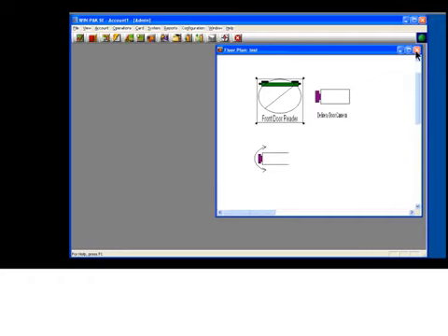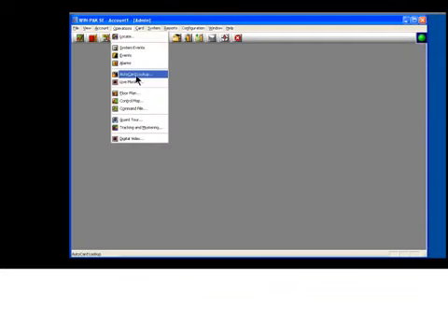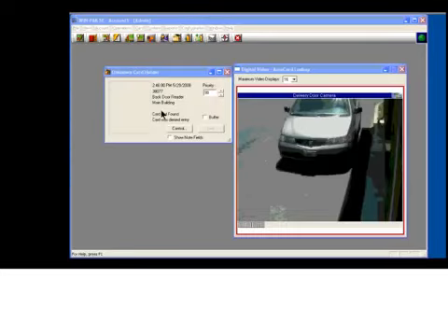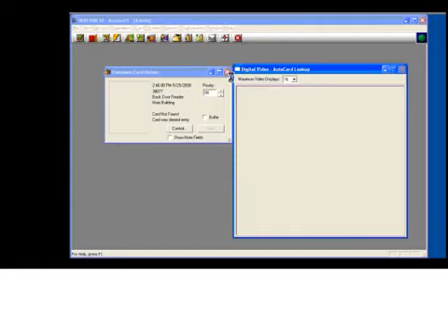All right. A couple of other features that you have when you're dealing with integration under Operations is something called Auto Card Lookup. And Auto Card Lookup gives us the ability when a card is swiped, you'll see the pre-recorded picture of the person, and then every time they swipe the card, you'll see the camera that's related to that auto card pop-up. So maybe it's a main entrance, maybe it's a vault door, maybe it's at a health club and they want to just record and do a comparison. Now, based on the alarm event, you'll have a pre- and a post-recording time set up by the DVR, and that's the information that you'll see when the recording is pushed back into the Winpak software.